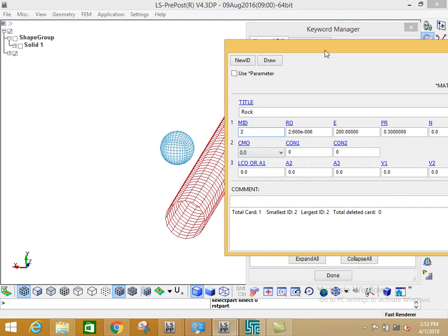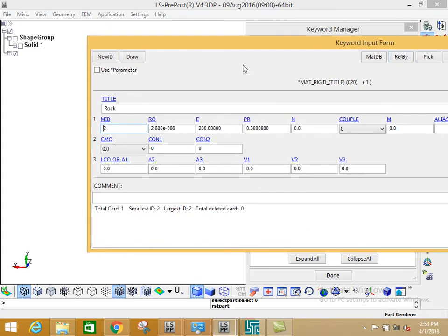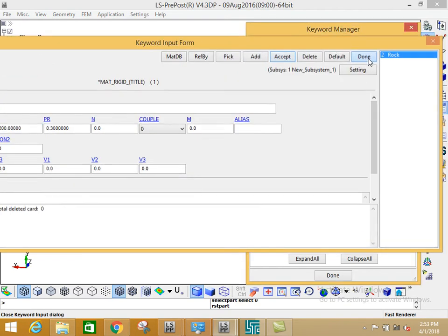If you model everything, and as I said we are interested in the pipeline, we can say this guy is solid. The actual weight of this one is, let's say, 500 ton. To achieve the weight of 500 ton, we can play with the density of the material. Understand? Because if we increase the density, the weight of the material will be heavier. That's a simple trick for you to know, it might be useful later. Now we accept. Done.